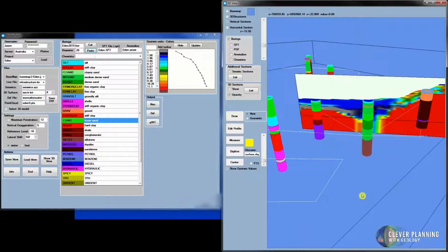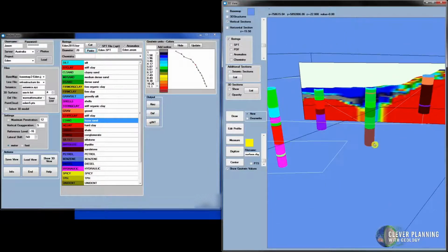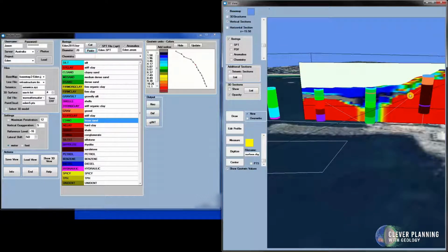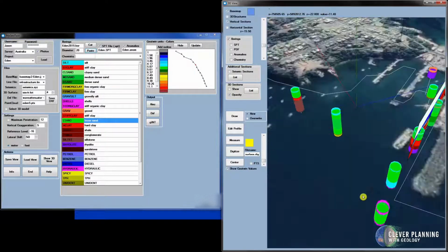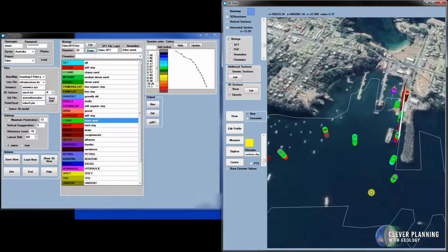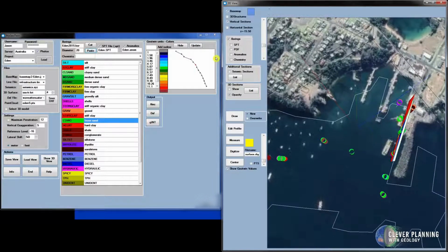Firstly, we can see that the boreholes in the advanced geophysics align perfectly at the point locations of the boreholes. The vertical feature between the red rock and the structures is visualized correctly. Let's just turn the base map back on for context, and immediately we can see that the straight line between the boreholes badly misreports the rock heights between the boreholes. Misreporting of the rock heights is a major reason for construction failure.